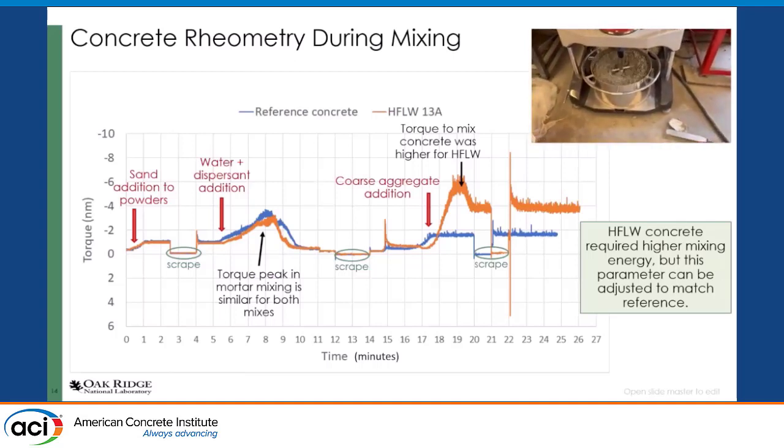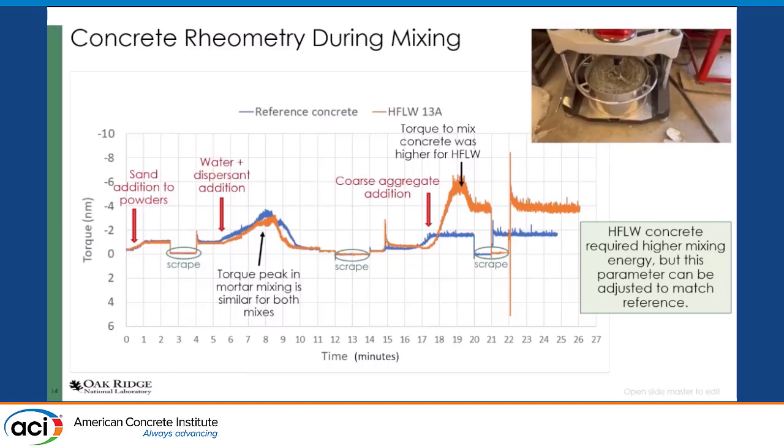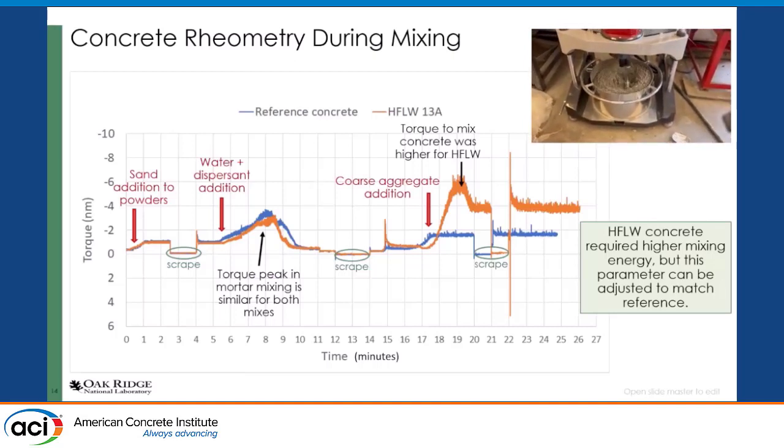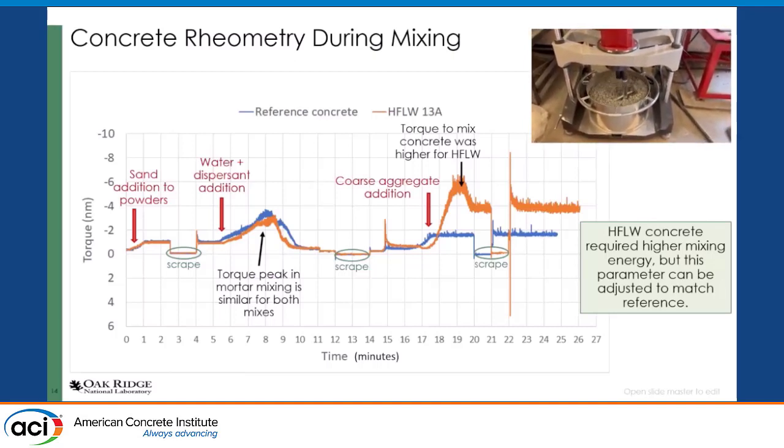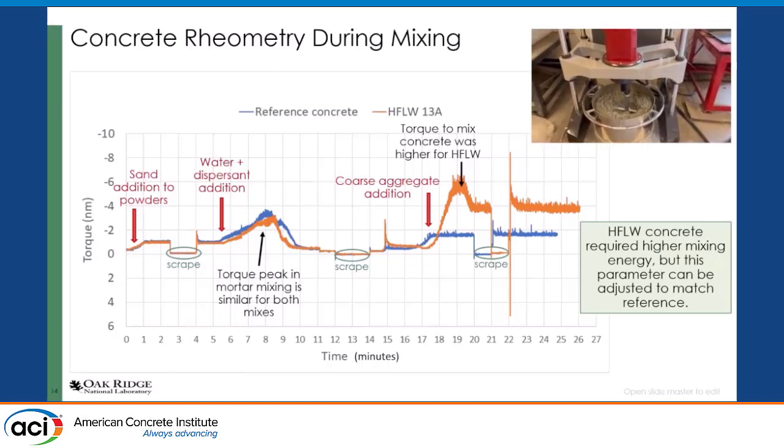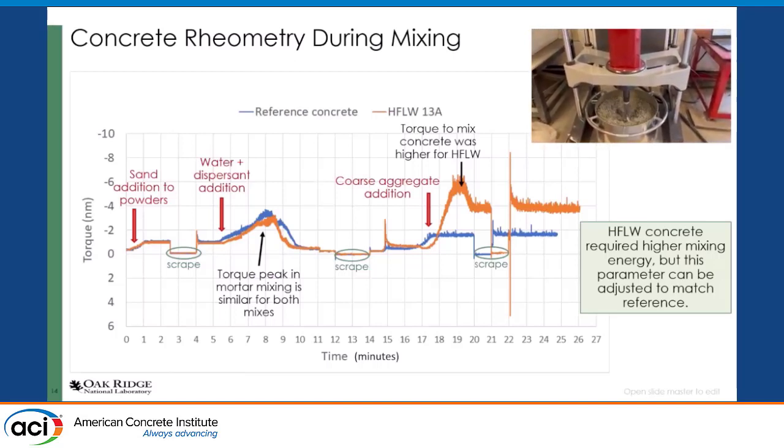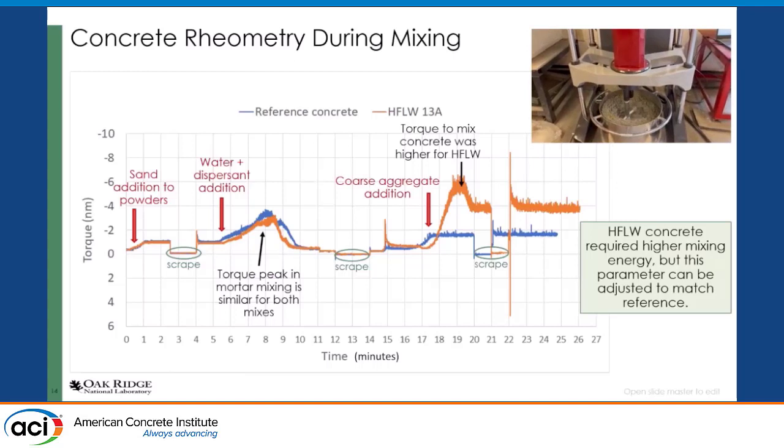We are not saying we're going to mix the concrete for 25 minutes. Just for your information, it mixes in 9 minutes in a drum mixer as well. Here we just wanted to see what happens. So first we add the powders, then we drip the water with the dispersant. So water comes after the powders and the sand.